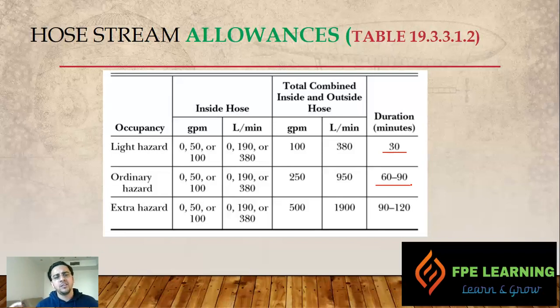Just consider the inside hose as nothing but a large orifice sprinkler which can supply up to 100 GPM. Just think outside the box. In warehouses, we have sprinklers which supply up to 100 GPM or even more than that. So just consider it like that and include the flow only, not the pressure.